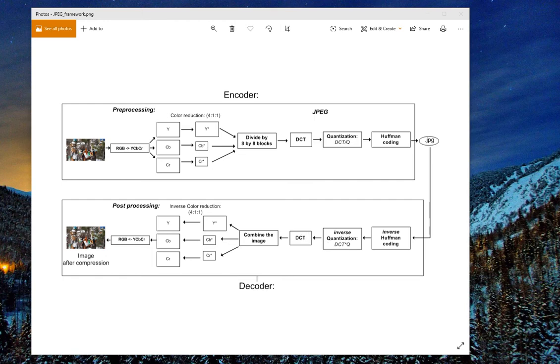Next we will process the inverse discrete cosine transformation, in order to get the pixel domain 8 by 8 matrix. That pixel matrix will be moved back into Y, CB or CR, depending on where the initial 8 by 8 block came from.